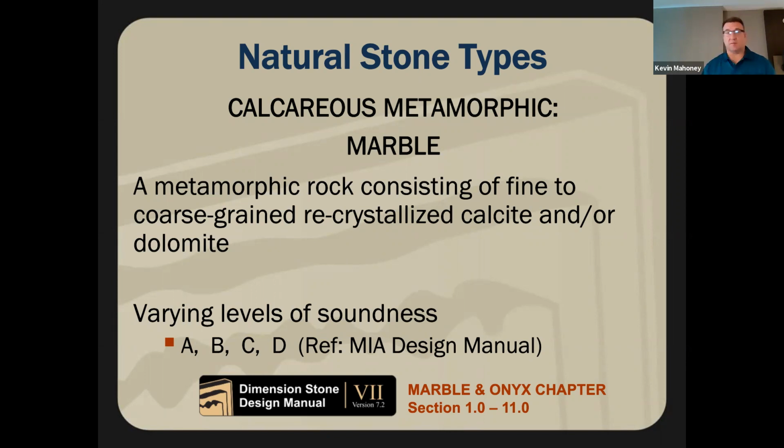Marble can be susceptible to water sensitivity depending on the species or where the marble comes from. So it's important to ask, is my marble water sensitive? Can I put it outside? And a lot of marbles we can put outside vertically. We'd never put them on the ground.